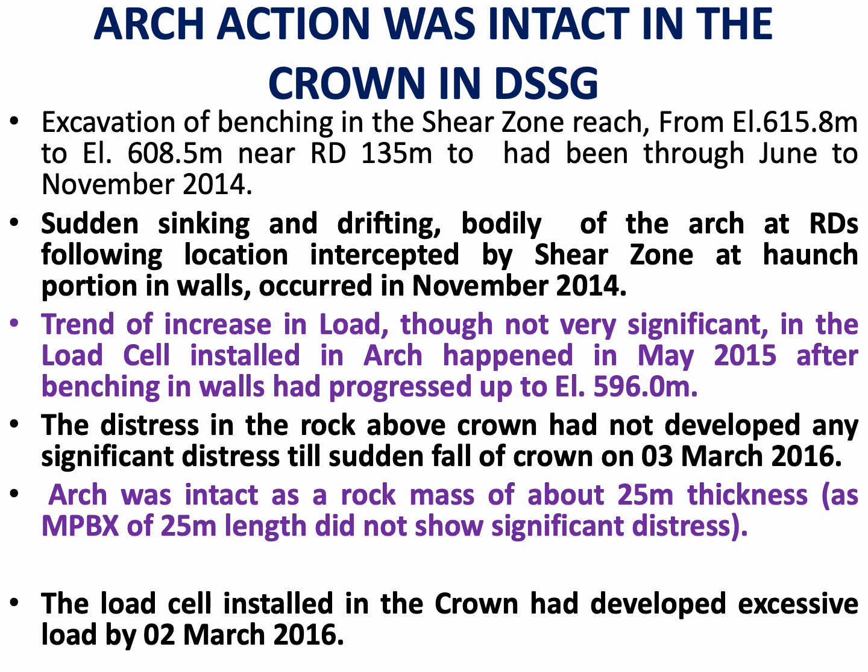Therefore, it can be said that an arch of at least around 25 meter thickness was intact till 3rd March, when distresses were also seen developing in the MPBX. The load cell installed in the crown had developed excessive load by 2nd March 2016. So only on 2nd March 2016 was there excessive load shown in the load cell in the crown.